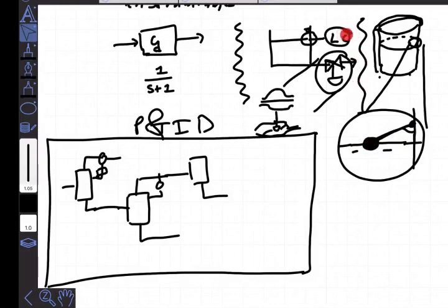There's a transmission network that then transmits signals from there to the controller. There's a controller which we've analyzed in great detail, but which will actually take the form of some physical hardware, whether that is a PLC, programmable logic controller, or distributed control, a piece of hardware that you could buy off the shelf called the PID controller. That's then connected to a final control element. That final control element is physically wired in or bolted into the plant. And all of that is what we're thinking about in Chapter 8, right? In Chapter 8, we're learning all about how these